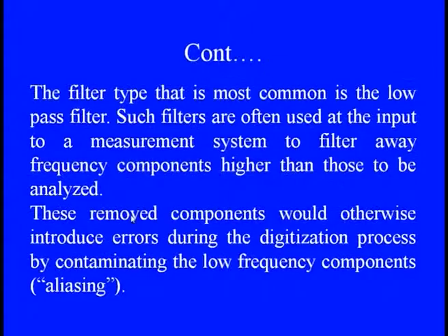As we discussed, the most common filter type is the low pass filter. Such filters are often used as the input to a measurement system to filter away the frequency components higher than those to be analyzed. These removed components would otherwise introduce error during the digitization process by contaminating the low frequency components, which is the aliasing effect.